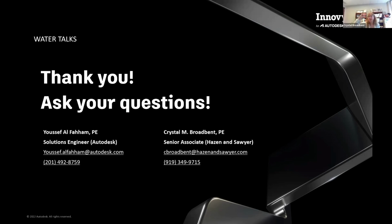So here's the thing, because there's only one data set, if you are doing a pump trip, that pump trip will trip in every scenario you have. So you can either use your facility set and deactivate the pump you're not interested in, activate the one you're interested in. If you're trying to do like, hey, I want this pump curve with this inertia versus this pump with this inertia, which one's better for transient? You can still create scenarios. You just have to do it through the facility manager and not through the data sets.